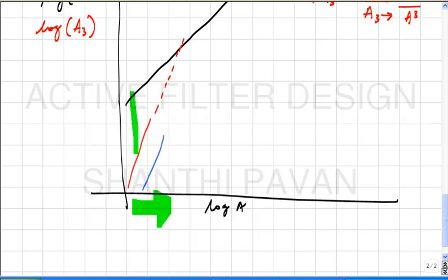How do we decide on the input amplitude? You have to make sure that this line is lower than which line? Fundamental. Yeah. Okay. Please note that it's impossible for it to exceed, because even if the output is a square wave, the third harmonic will always be smaller than the fundamental. You understand, right? So as long as you don't overdrive the filter, you will find that this holds. In principle you're only interested in these lines. You know that they're straight lines, so in principle you need only 2 points. In practice you'll have a few more points, get a best fit straight line, and move on.